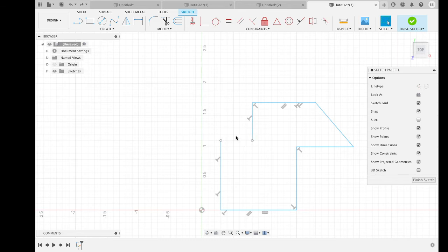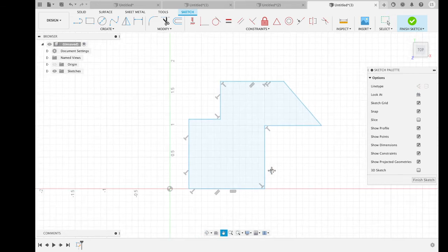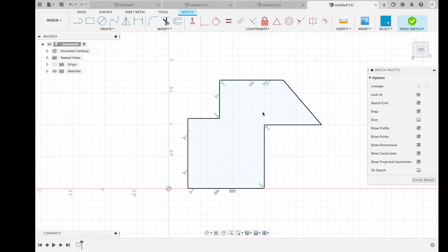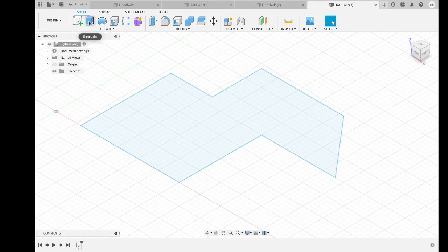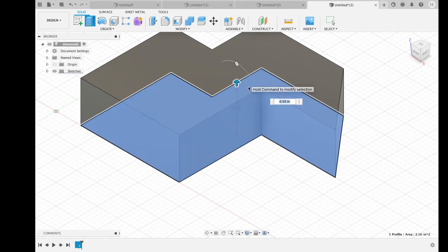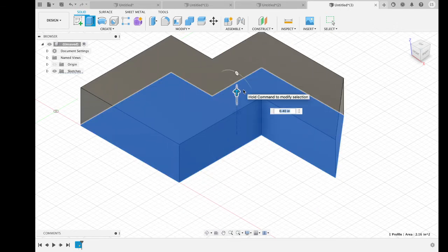So that means you haven't yet created any shapes, an actual object. You just connect the lines. To make a shape, you need to connect like this, and you made a shape, right? So we can use these shapes to make your actual 3D object. If you finish the sketch, you can click this button, and you're finished. You draw this sketch. So using your sketch, you can extrude like this, or you can add other objects in here. All right. So this is sketch.